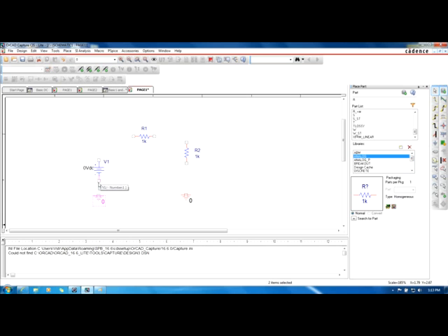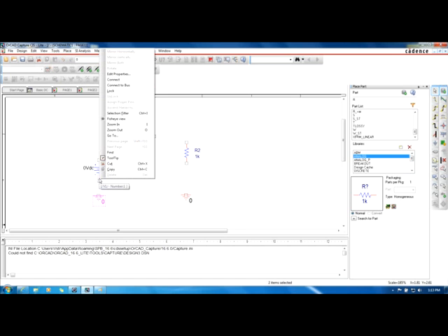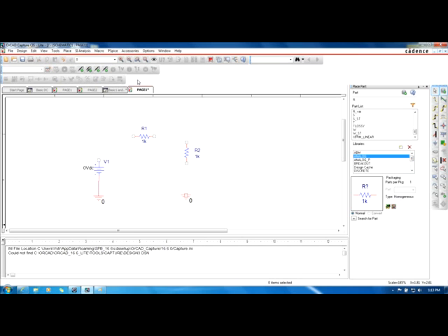Okay, I hit Control when I did that. I clicked on something, and then I pushed Control and clicked on another thing. And I can say connect. Not connect to bus, but just connect. Okay, and it automatically connects it. See, I can do that. So if you're having trouble aiming, then you might want to do that.